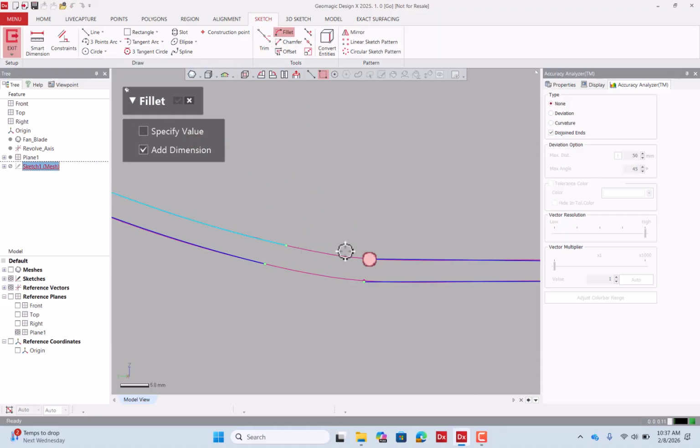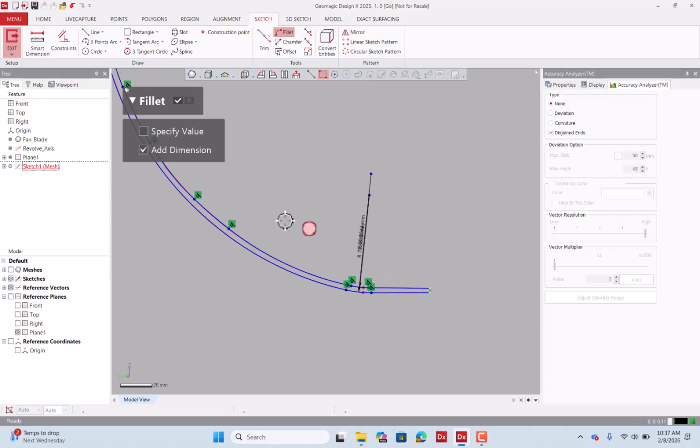You can click on this arc, and then click and hold on this line and move your cursor and place it appropriately so that they're on top of the trace. So I can click on segment 1, then click and hold my mouse on segment 2 and move my mouse and place it so that we are on top of that pink trace and say OK.